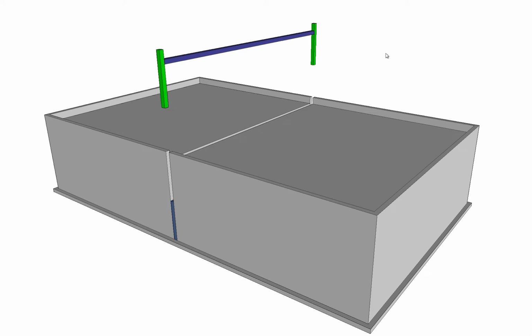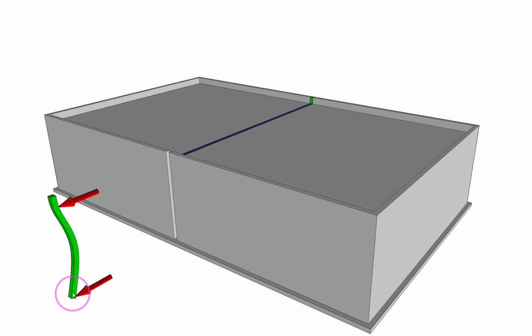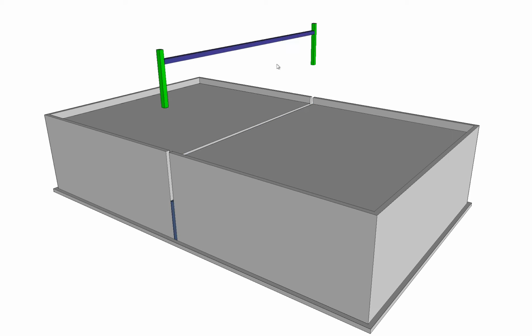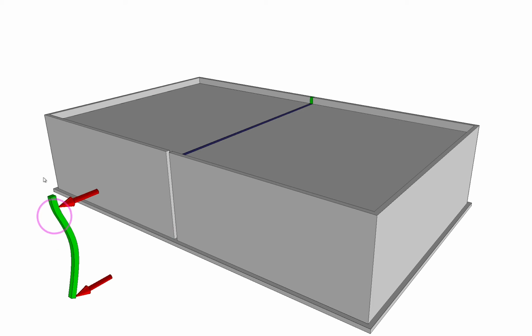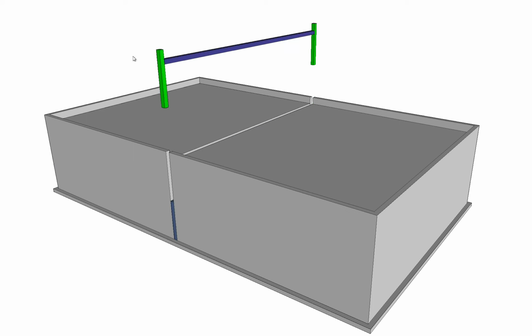So this view now shows a segment. Because we're spanning from the ground up to the roof, essentially half of that load is going down to the foundation, and the other half, plus this little piece, the 2 feet at the top, those are being supported by the top slab. So we can extract that half because, again, half of that load goes down to the ground, half goes up to the roof. We extract that portion of the wall plus this portion of the wall and a segment of the roof, all of which are 1 foot wide.